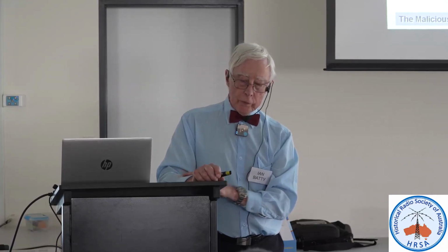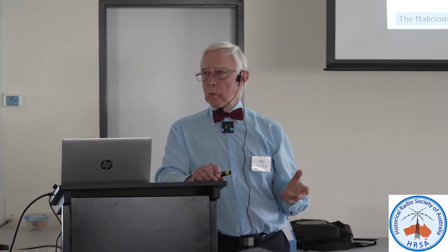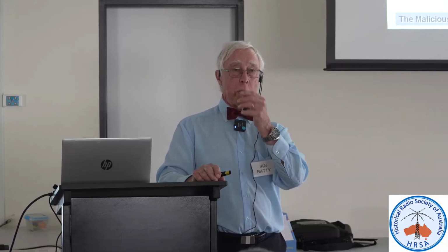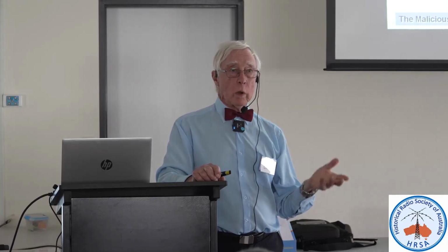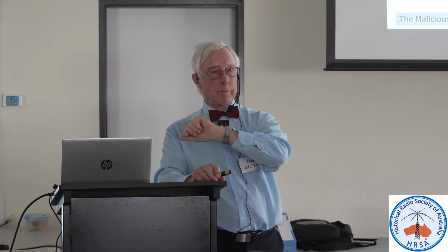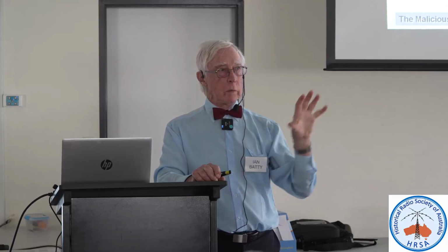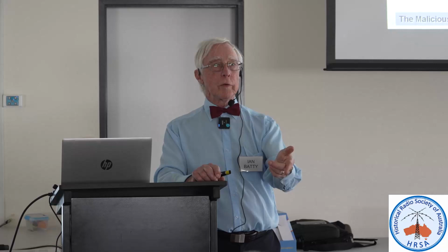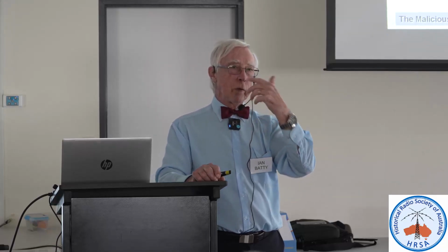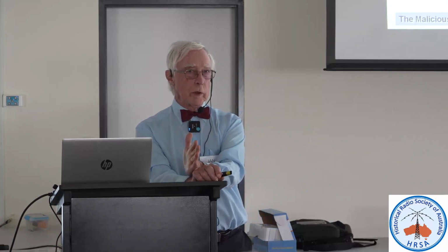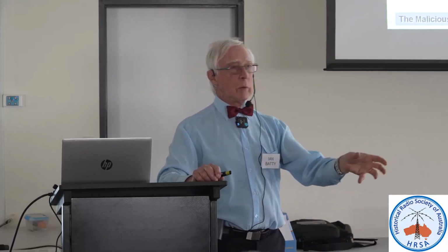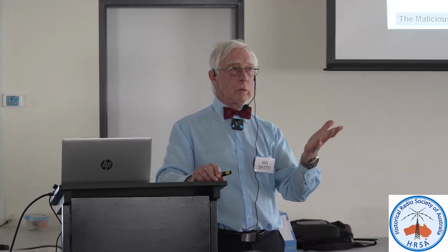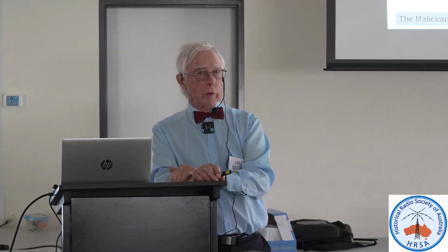Yes, I guess what I call it, I take a sort of operational approach. And just to take that point of power consumption, what I'll do is I'll pull out all the valves and then put it on the tester. Sorry, pull out all the valves except the rectifier. Sorry, I'll pull out the rectifier and leave the other valves in. Okay, that's what I meant to say. Then put it on my test bench and bring it up. I haven't got the rectifier in, so there's no risk of electrolytics exploding.